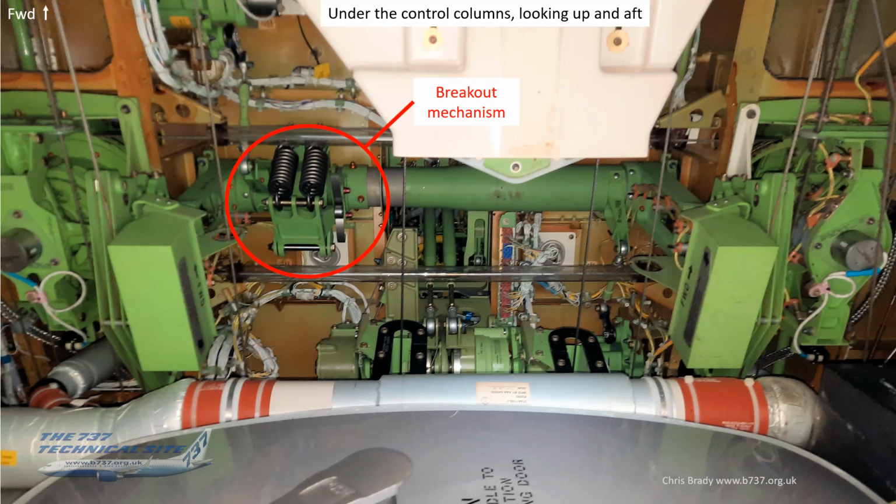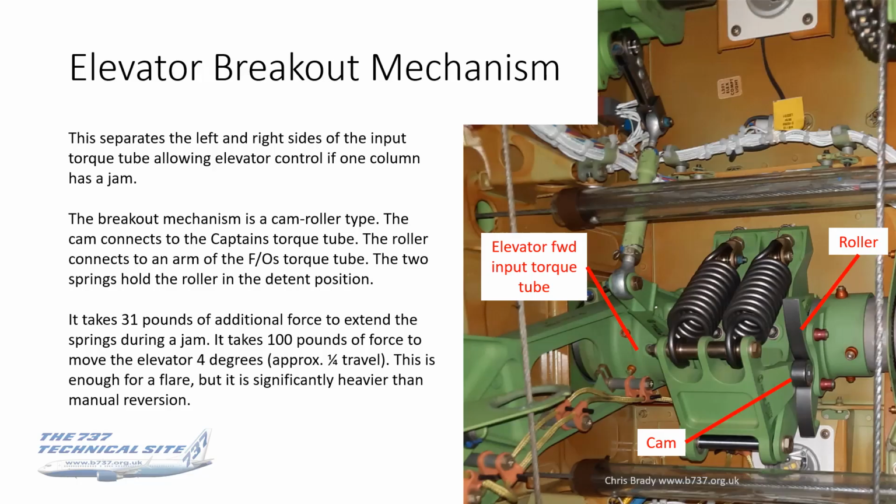I mentioned the breakout mechanism, the possible independent movement of the controls in the event of a jam. I've highlighted it there where it is, so that's where the breakout mechanism lies, and this is an enlargement of that area of the photograph there. So what this does is it will separate the left and right sides of the input torque tube, and that allows elevator control if one column has a jam.